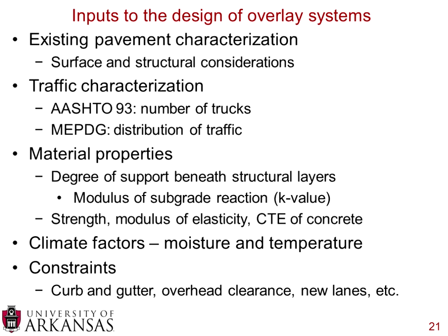Because if your paste is expanding and contracting at a significantly different amount than the aggregates, then you could actually have debonding of the paste from the aggregates. And then essentially you have a very glorified, expensive gravel road because you no longer have that bonding, your concrete starts deteriorating, and you just have paste chunks and aggregates. So you want to try and match up the coefficients of thermal expansion.